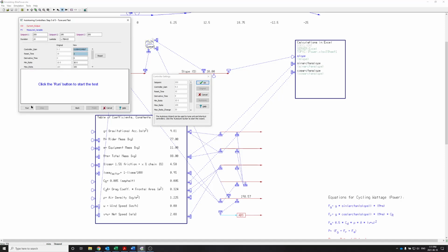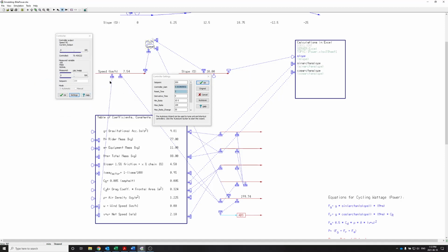Let's click next. Let's run this guy and find out how good it's tuning. It seems to be relatively nice. It's a bit jaggedy, so we can use lambda tuning to try and smooth it out a bit. Let's use 5 here. We get a slightly smoother approach. I think we're happy with that, so let's click finish.